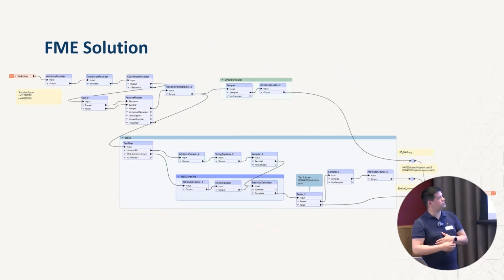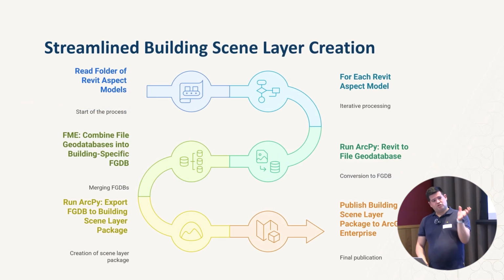Well, and the workspace kind of looks easy. I read those site points. I have to generate the projection file for my BIM models. And I have to make maybe a transformation, and we do that with, as I mentioned here, the universal world file or a specific one for a model. And then my data is on the right place.